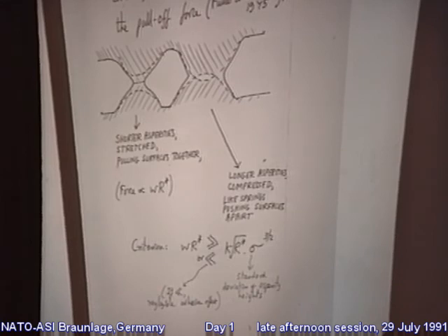On the other hand, the two asperities that I've got on the right, they want to overlap. They're longer ones, and therefore, in order to reach equilibrium, you've got to compress them. So they become like compressed springs, tending to push the surfaces apart. And so it's this variation in height of the asperities which is responsible for that. But it's very difficult to observe any measurable pull-off force with rough surfaces.